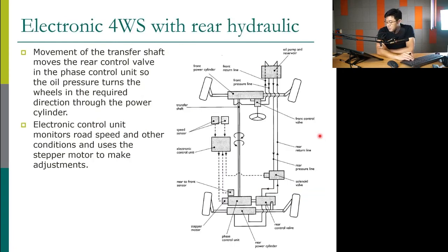We also have rear wheel steering which is a hydraulic system. This is the rear hydraulic. Basically, it is similar to power steering. They use hydraulics to control. It has a shaft connecting the front and the rear also, and that shaft is used to control some kind of valve inside here.